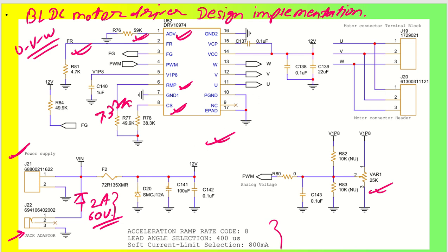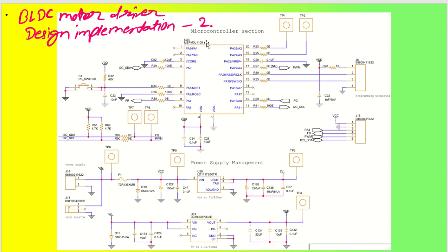Coming back to one more design, what we did is with the microcontroller section. This was a standalone design, a very simple design. If you want to reduce the cost and just keep it in your fish pot motor drivers, or maybe any toys, or any blowers or fans, this is very easy to work. However, if you want to control the motor speed through a microcontroller, then we can utilize this one. What I have done is taken a very simple microcontroller, which is the MSPM0L1105,